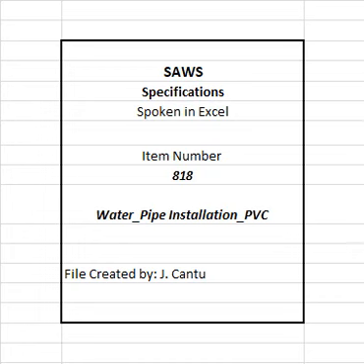5. Testing reports. A. Furnish affidavit certified that all pipe meet the provisions of the specification and has been tested and submit reports in accordance with the applicable ASTMs and AWWA standards. Reports to include the following. 1. Hydrostatic proof test reports. 2. Sustained pressure test reports. 3. Burst strength test reports. 4. Stress regression testing. Additional reports may be requested by SAWS inspector.